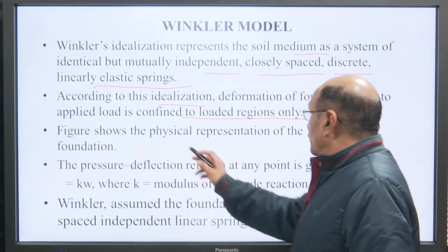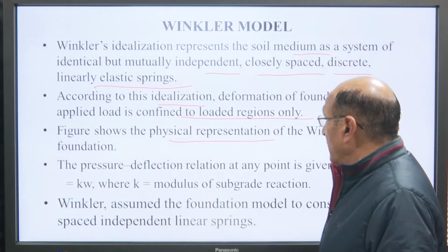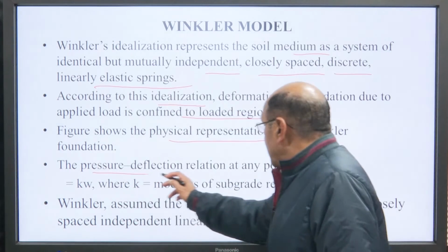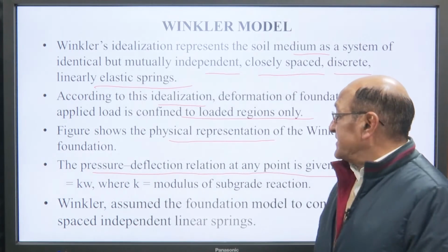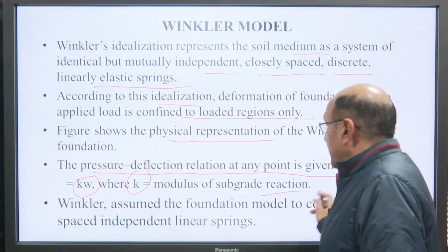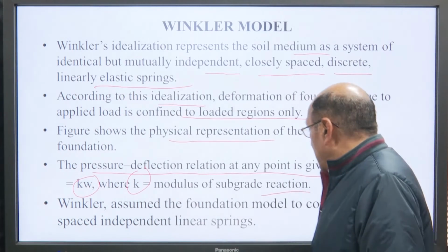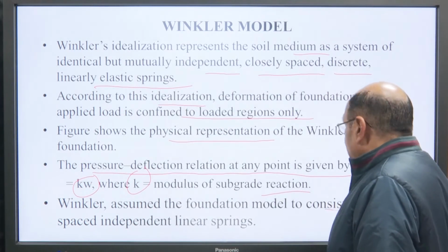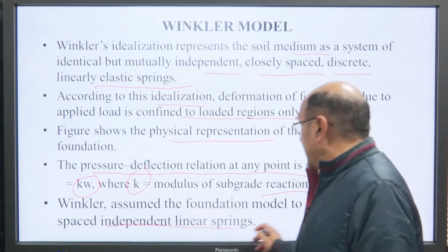This is the main thing of this Winkler's model. So, the figure shows the physical representation of the Winkler formula. The pressure deflection relationship at any point is given by k w, where k is the modulus of subgrade reaction. Winkler assumed the foundation model to consist of closely spaced independent linear springs.